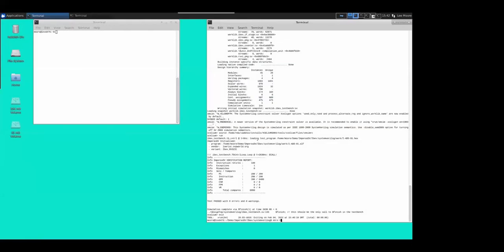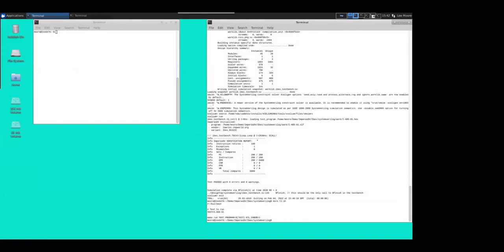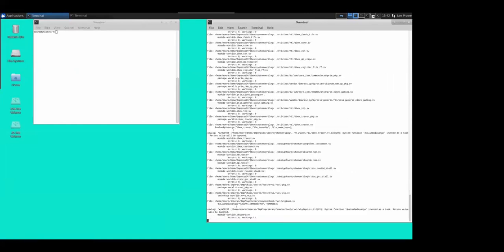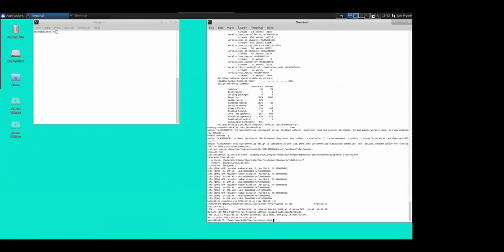So let's just have a look at the script that we're going to run here. As I mentioned, we've got this tick define that's going to be enabled. And if I now run this, let's see what happens at this point. So again, we go through the elaboration phase. I've actually got this configured at the moment to tolerate 5 miscompares, and this is programmatic. We can say how many we want it to absorb before it goes through to a bailout condition.